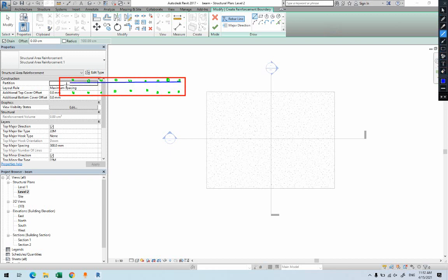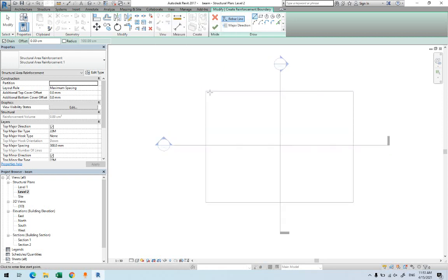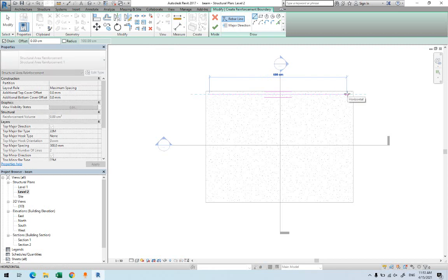and sure you have the bars at the bottom in the other direction as well. So this means you have bars in this direction and the other direction, so you have bars in two directions. This can be used as area bar. Now when you click on the area, it's totally different than the normal. You have rebar line, so you draw a line somewhere. For example, I start somewhere from here and draw the line. I know the length of it, still there is no hook here, we can go back and change those dimensions. This is the bar that I'm drawing here.